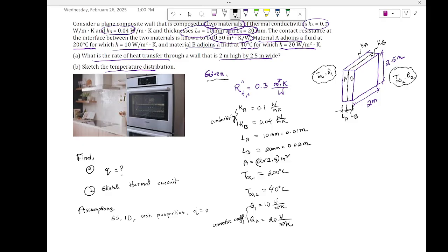If I were in your position, I would start by putting the temperatures on the thermal circuit, right? There are two different temperatures given. Now the question is where those temperatures are. That is the important thing to understand. One temperature is outside, another is here. They said it's fluid. Let me correct myself: one temperature is the outside fluid and the other is the inside fluid. So where would you put them? On the thermal circuit. That's something to think about, okay?